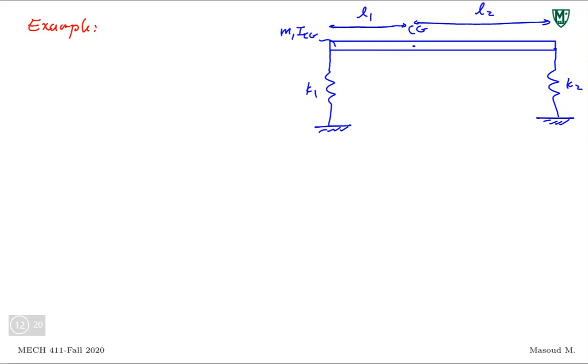That's pretty much it. Why does this one have 2 degrees of freedom? Well, 1 degree of freedom would be its vertical motion, going up and down, up and down. The second degree of freedom would be because if x1 and x2 do not have the same stiffness, if they have different stiffness values, right? So you have a bar, I do have a bar here as a matter of fact.